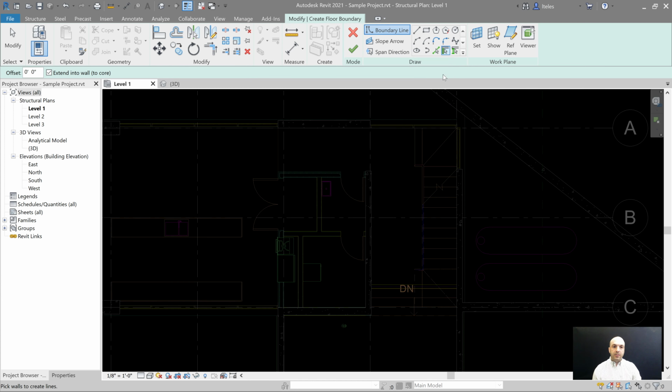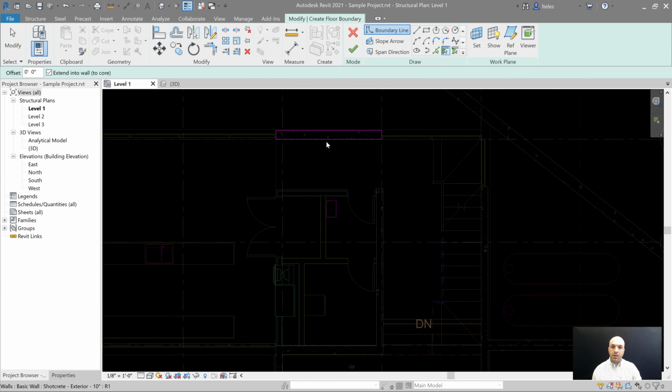The beauty of that is when I pick this concrete wall right here, there's this little toggle, right? And Revit is basically communicating back with you. Do you want the edge of this floor to go to the outside, or do you want it to go to the inside? Well, we think about phases. On a slab on grade project, where this is the foundation system that is used, the slab on grade is the last thing to be poured. So now we translate that workflow into Revit.